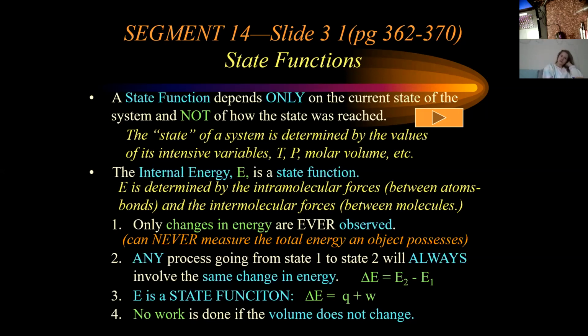So when we use these devices in lab, you always put them behind the blast shield, and you get way away from there when you push the button to cause the reaction to take place inside. You don't want your bomb calorimeter to be just a bomb. You want it to hold together, because you're depending on no boundary moving, and that causes the work to be zero.